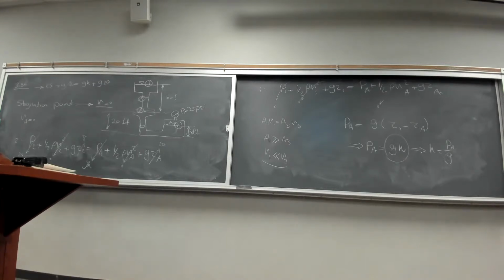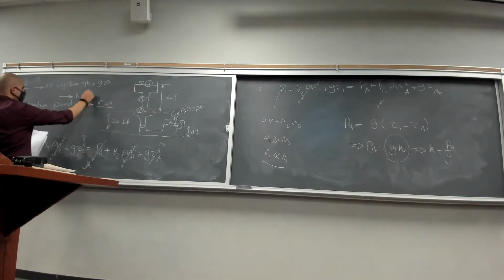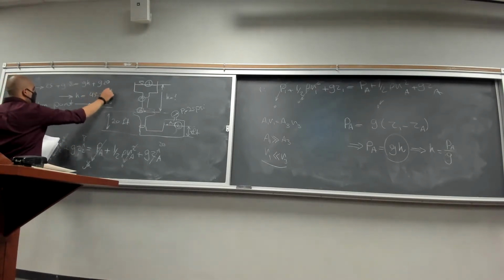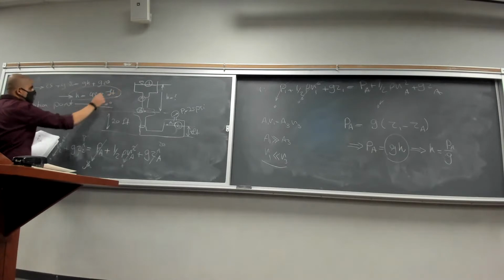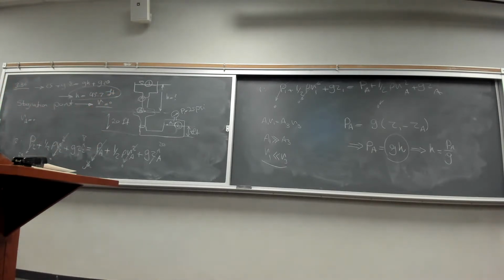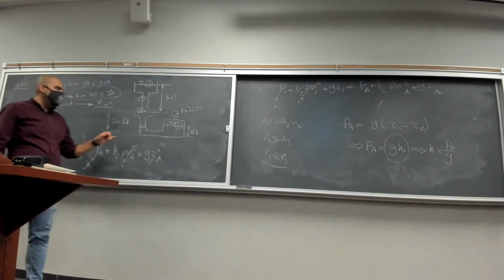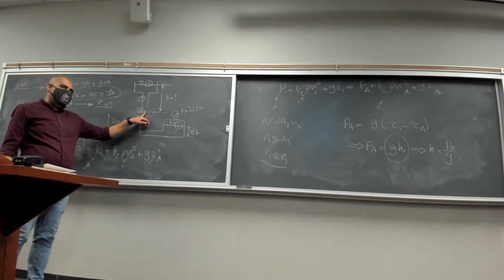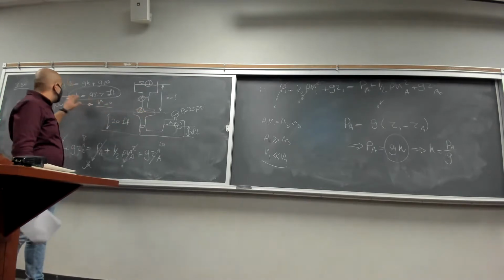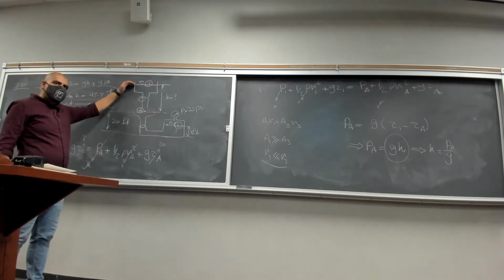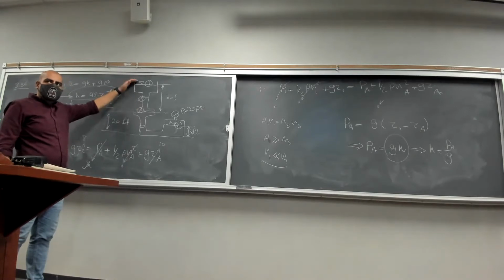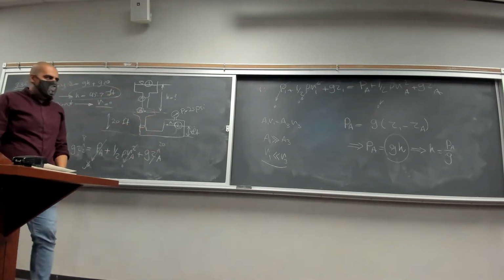You plug in the values you have for G, and then you are going to calculate your H, which is equal to 45.7 feet. What does this mean? This essentially means that if you want to get a stagnation point at point A, this surface has to be 45 feet above point A for this specific condition. Okay?